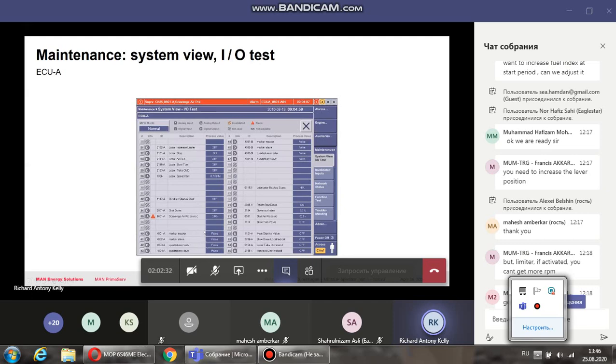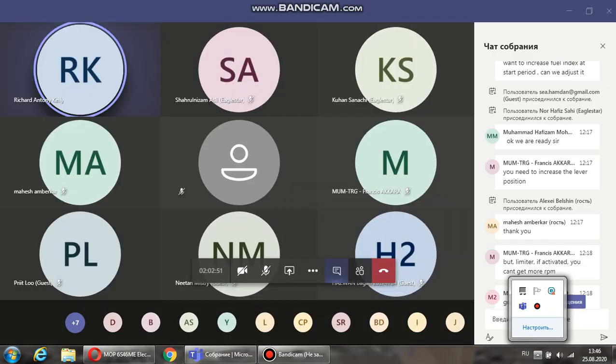Can you remember we need to have 4 valid values for your angle encoder A and the same 4 valid values for encoder B. Remove one of those, the system thinks it has a failing encoder, therefore you are taking your encoder out of action. So therefore they are the only ones that you cannot invalidate. Okay, gents?